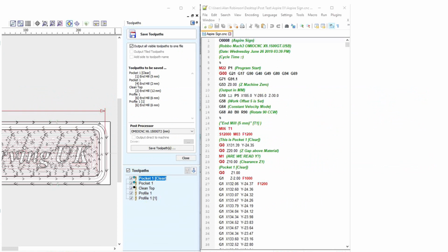Let's start by looking at the output from this post processor. Line 1 is the job number in a way which is recognized by most professional machines, 00055, followed by a comment, normally a drawing number or title, but here just a file name.